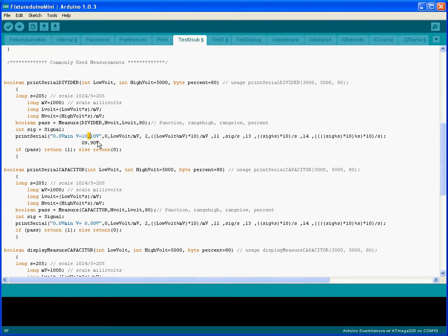the whole time. If you use floating point, what's going to happen is you're going to get results flashing between here and here. So the decimal point is going to be jumping around the display, and your display is going to be flashing, and it's just going to look messy. So with using the modulus techniques, you can have it display something similar to this.